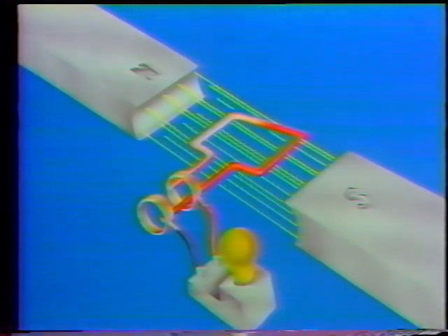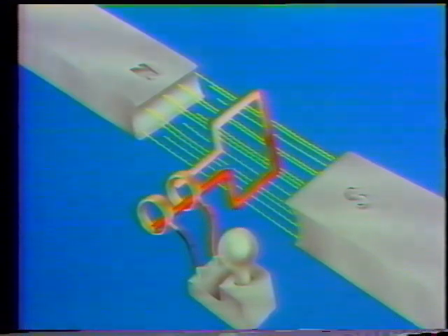The position of the conductor in relation to the lines of flux also determines how much voltage you have at any given point. When the conductor is in this position, it's cutting through the fewest flux lines, so it puts out almost no voltage. But in this position, it's cutting through the maximum number of flux lines, so it's putting out the maximum amount of voltage.